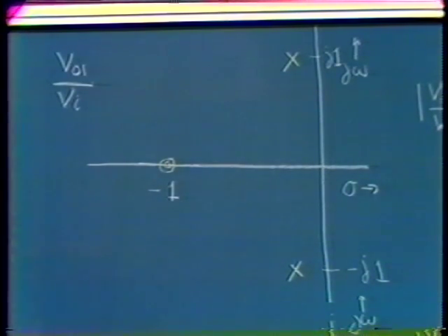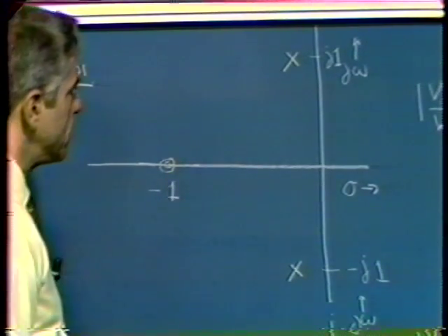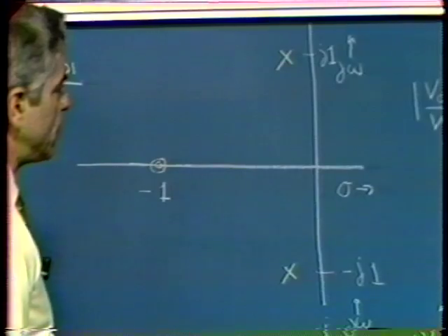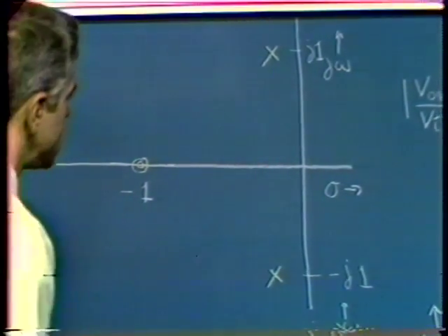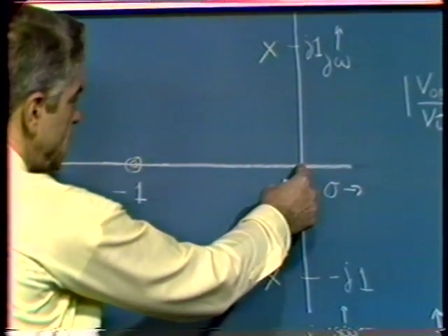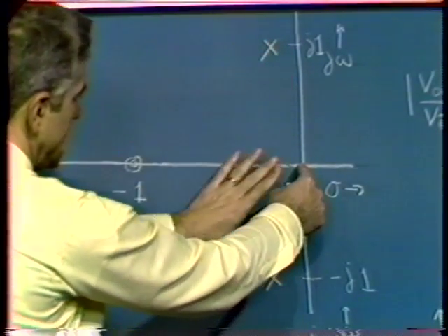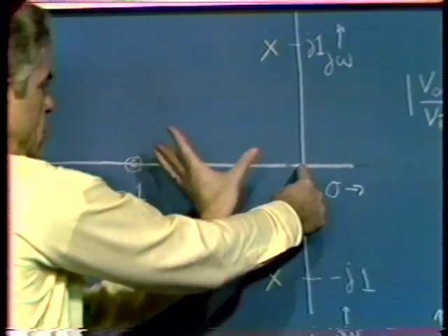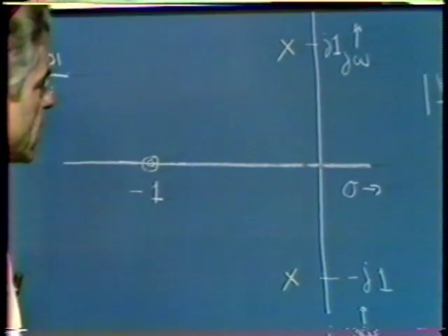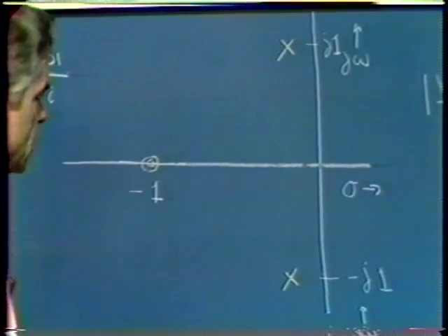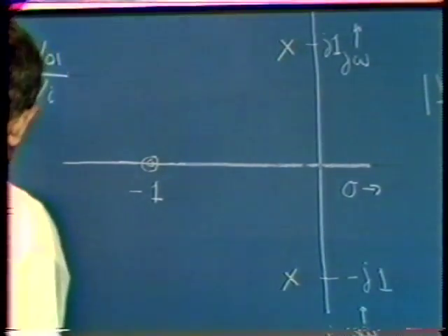And we can sort of rapidly sketch the frequency response of that system with the usual vector manipulations. We recognize that at DC, the lengths of the vectors from a pole and a zero cancel. And since there are two poles and two zeros, we'd at least have a magnitude that we might normalize to 1 at DC.